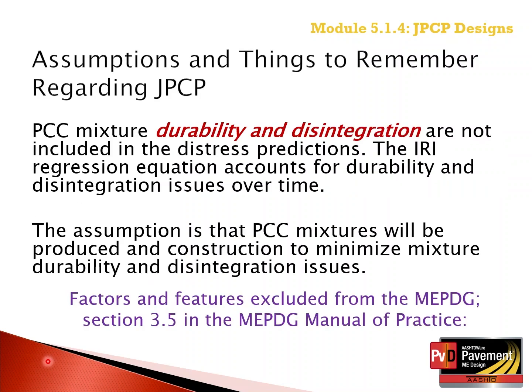As mentioned in the MEPDG Manual of Practice, under Chapter 3.5, Factors and Features Excluded from the MEPDG, durability and material disintegration of the PCC slab, as an example D-cracking, is not predicted by the software. It is assumed that the PCC materials and mixtures will be designed to prevent any durability issue from occurring throughout the design life.